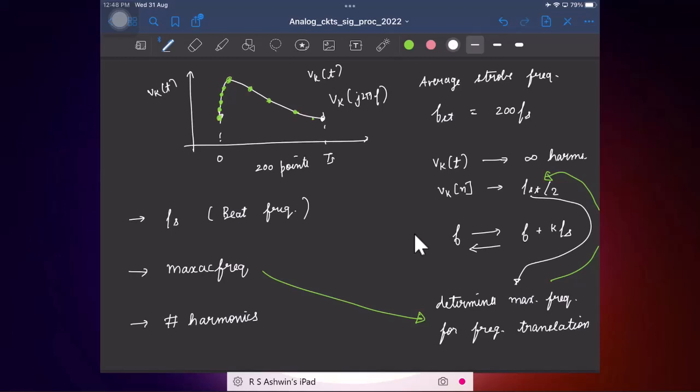And that's because by default PSS computes only the time domain information, right? As we saw, it assumes an initial guess and computes the time domain information. So if you want to know the frequency spectrum, the tool needs to do additional calculations and show the spectrum.